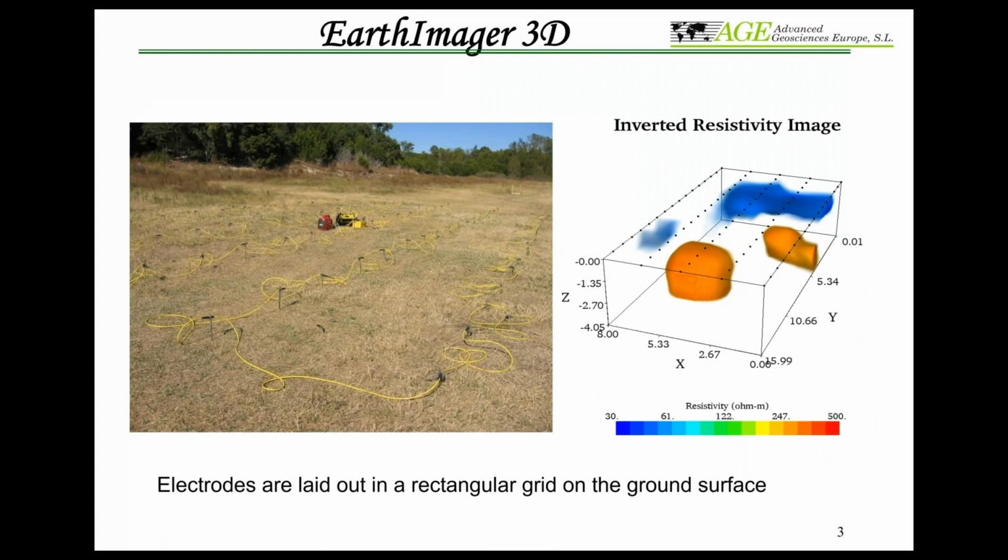Typically in a 3D survey, you generally go through like this. This is a 3D layout. So start your electrodes from one corner, and then you just go through. Let me change this to go through like this, and then go back over here like this, or the other way around because of the cable here.